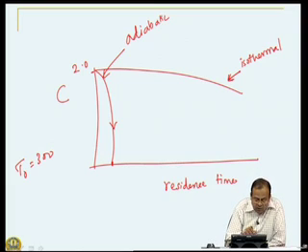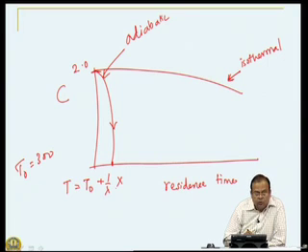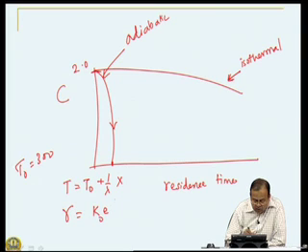In fact, the behavior is very similar at the starting point because conditions are the same, but what happens in an adiabatic process? In adiabatic process, as our conversion increases or concentration decreases, in an exothermic reaction temperature increases. Now, what happens as temperature increases? Remember, this is our rate.